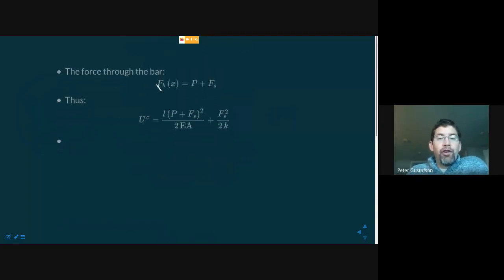We do need to differentiate the force carried by the bar from the force carried by the spring. And so, you can just basically do a free body diagram on a point here at the end. So here's the point force, and then the spring we're going to assume is adding in a positive direction. We're going to assume that there's a force from the spring, and then both of those forces would be carried through the bar.